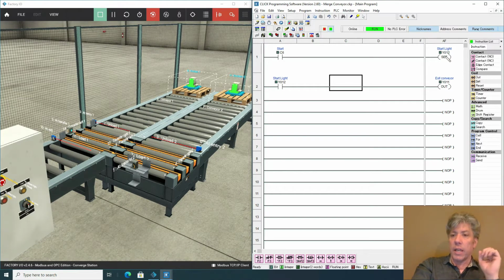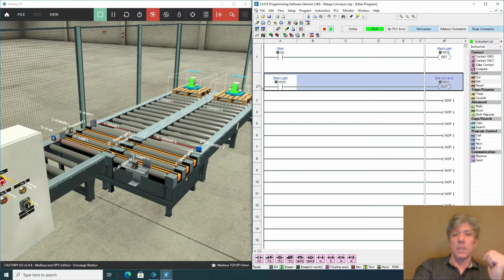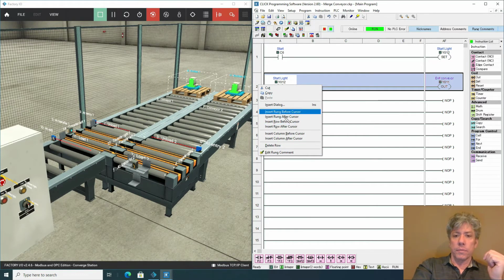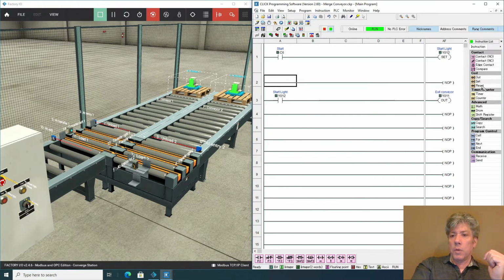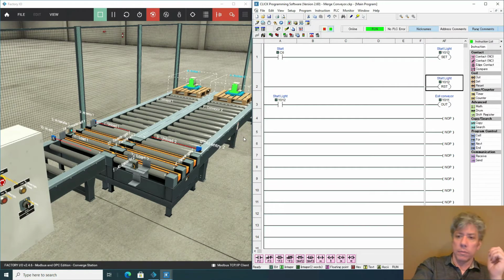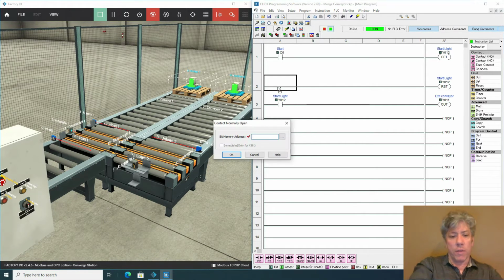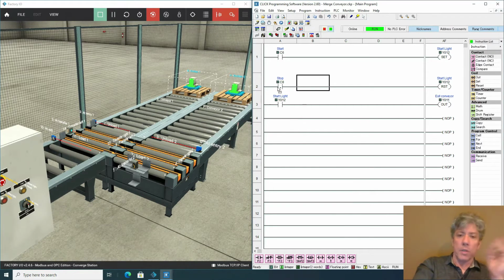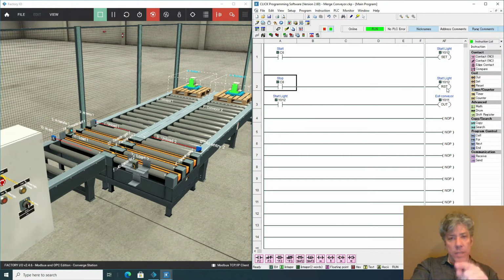It looks simpler, right? How do I stop it? Well, let's insert another rung. And we'll add a reset command. And what should the reset command do? Well, it should reset Y12. What's the condition for it? Well, we got to be careful here, because if I do this and I reference the stop button, it'll constantly reset the light. Here's the thing. The stop button's normally closed. That means this instruction would normally pass power, which means that reset is going to be triggered every time the PLC goes through a scan, which is going to happen thousands of times a second. So I don't actually want that.